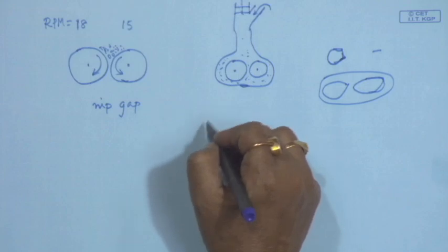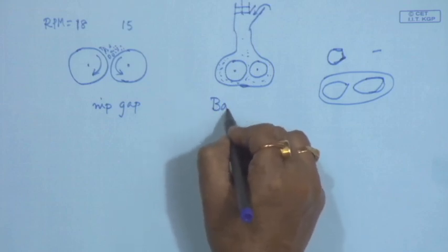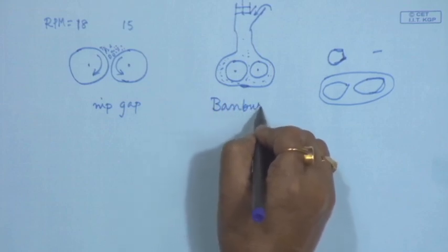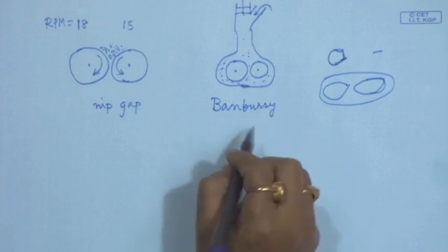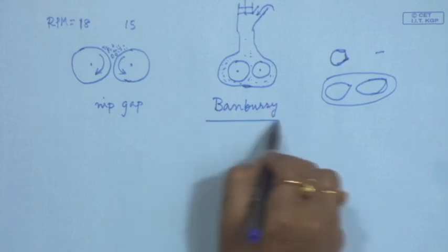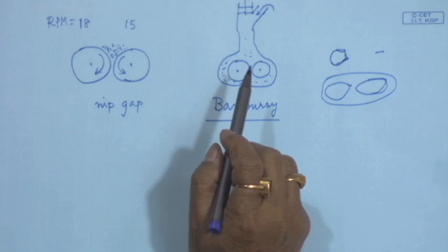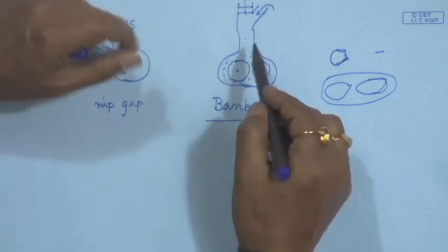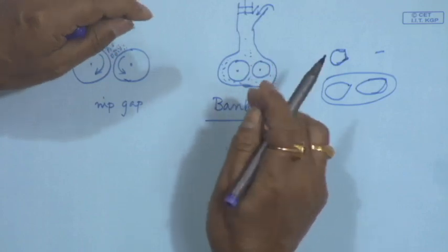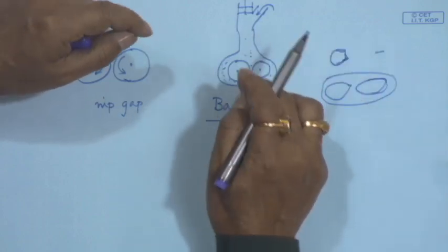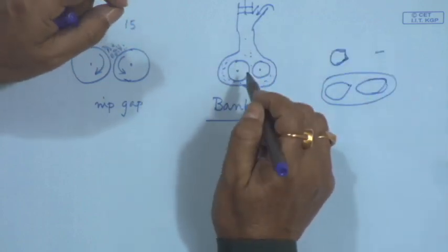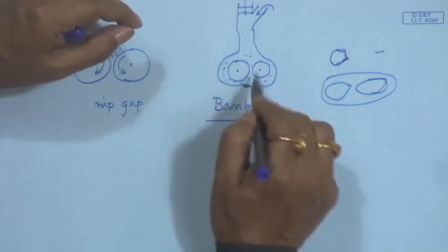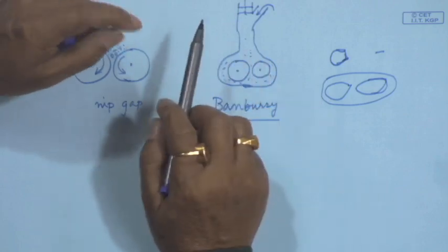There are various types of internal mixer, say Banbury mixer, or there can be many other names. So, internal mixers or kinetic mixers, these are all batch mixers, that means after mixing of one batch, the second batch is to be loaded, and then it helps in mixing. So, through shear action we get this mixing in this batch mixer.